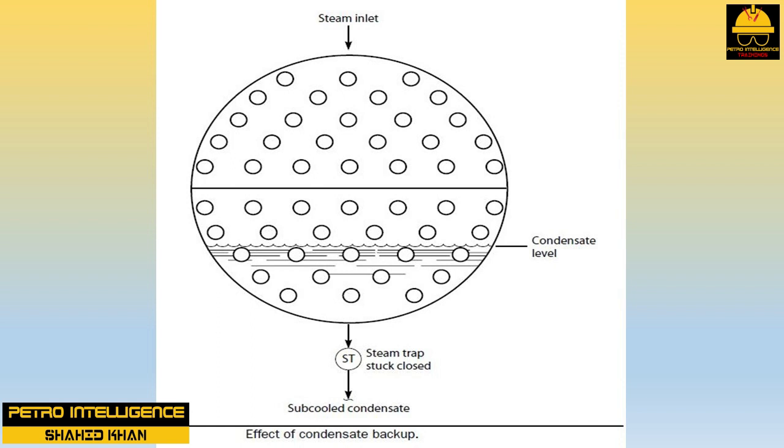capacity. If you think either of these two problems could cause a loss in reboiler duty, try opening the bypass around the steam trap. If the reboiler duty goes up, the problem was condensate backup. If the reboiler duty goes down, the problem might be a blown condensate seal. If it looks like a blown condensate seal problem, close the steam trap bypass. Then partially close the valve downstream of the steam trap. If this increases the reboiler duty, a blown condensate seal failure is proved.